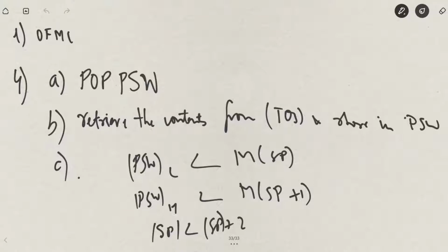The rest of the properties are similar to pop RP: single byte, 3 machine cycles, 10 T states, 3.2 microseconds. No variation here because pop PSW exists as itself. No flags affected. And as for the addressing mode, both source as well as destination will be implied in this case. Then you'll have the micro RTL: in memory read machine cycle number 1, the PSW least significant byte will be written, and in the next memory read machine cycle, the PSW most significant byte will be written.